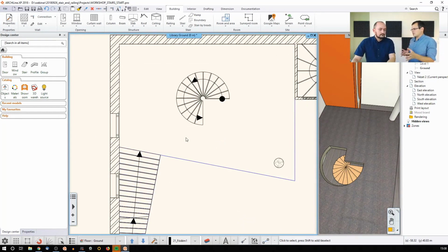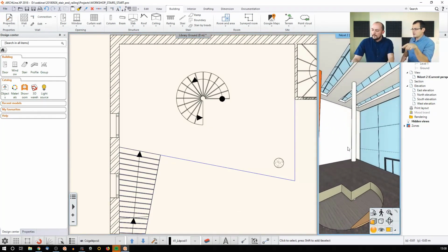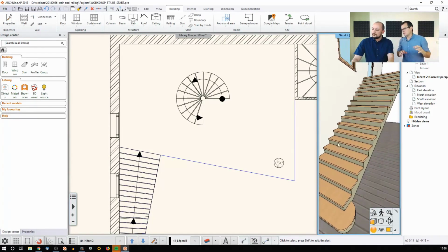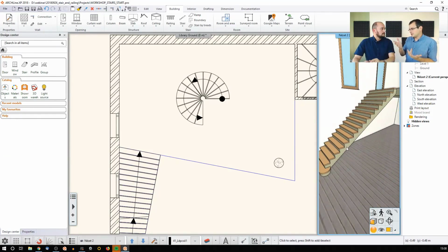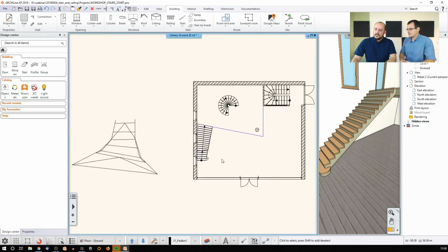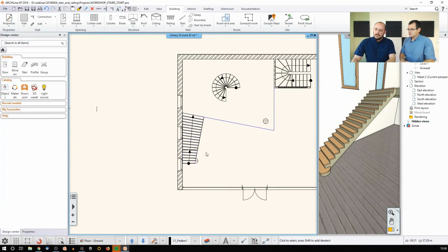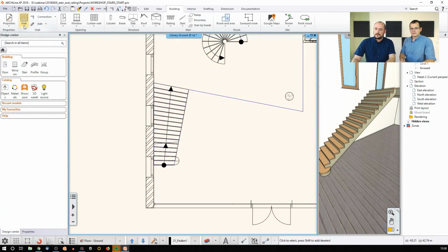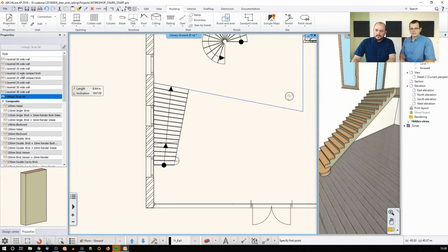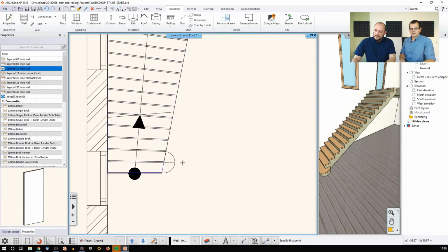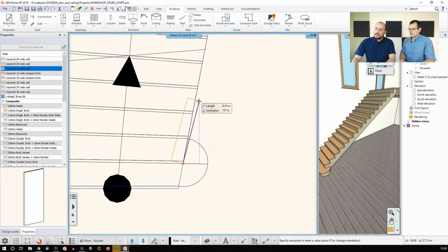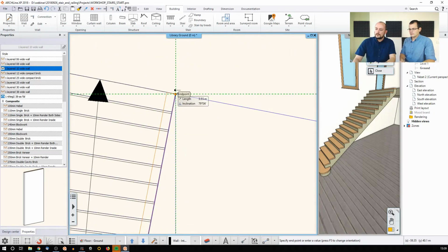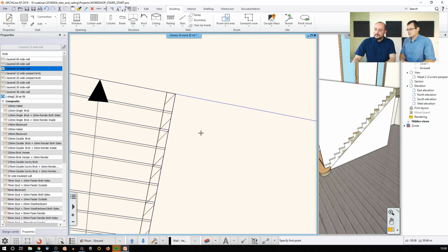Because I think that there are some scenarios when you want to cut walls with a staircase. For instance, if you go back to the other staircase, the irregular one, that's this one. If you want to add a wall under it, obviously you could add the wall and you can profile its section to match it, but maybe there's another way to quickly fill that gap. Yeah, luckily this can be automatically solved. Once you create this wall, I think I will just go with a 100 millimeter wide wall. So I will just draw a wall which starts, for example, from this point and goes below the staircase up until this point where it matches, which reaches the slab. And so by default, this is what I will get.